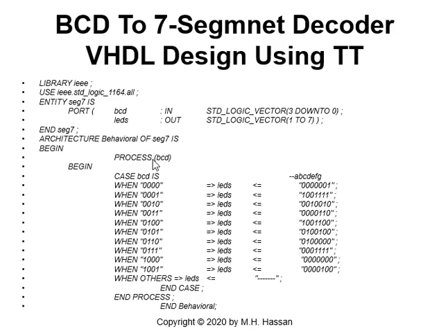The process between parentheses BCD. Now, why BCD? Because BCD changes values. The input changes values. So, beginning the process, we will use a case. The process will start with begin and end with end process. If we use case, the case will start with the word case and end with end case.